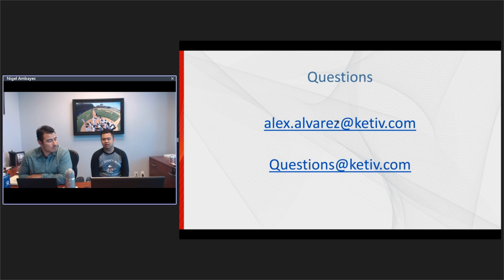I think Fusion's got many dozens of file types able to open natively. Like with all the other CAD software, when you're using that translator to open those foreign CAD files, you're not going to get things like design history. So you're not going to be able to see the sketches, you're not going to be able to edit the features for, say, holes or extrudes, cuts, etc. You're not going to be able to edit those directly unless you're in that native software. It's just how everything works. But at least you're able to open that file. And that's the big thing.